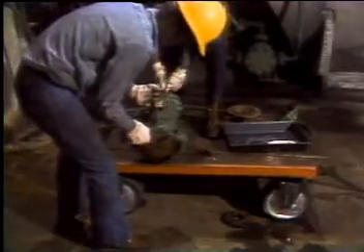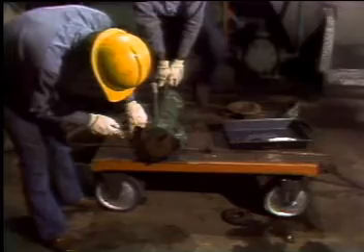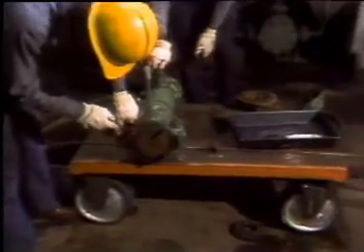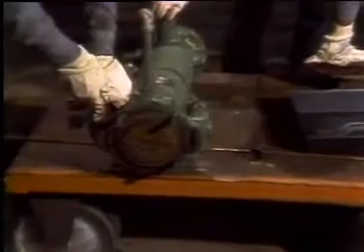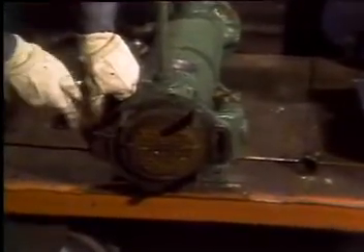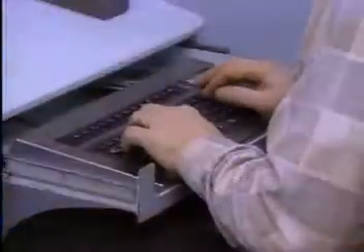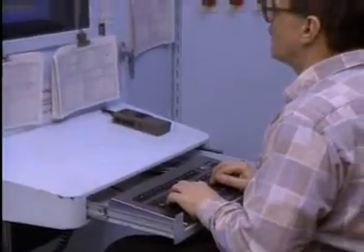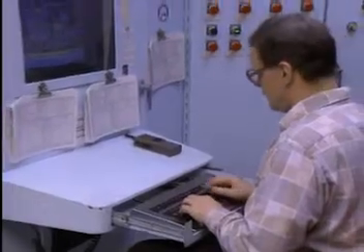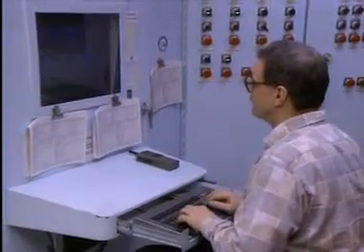When maintenance is performed on process equipment, air may be trapped in the piping or shell as the equipment is put back together. When the equipment is restarted, the air can make its way to the heat exchanger and become trapped inside. No matter how air or other gases get trapped inside a heat exchanger, they can cause it to become airbound or vapor-bound. There are several symptoms to indicate this.